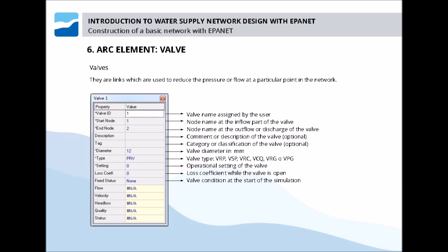Valves are quite specific elements, located at very specific points. And this is where we need to learn and understand that, in reality, these elements that regulate the flow are again specific and can be associated to node elements. However, in the mathematical model, they behave like arc elements, since they regulate pressure or flow from a node to the next.